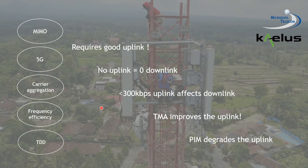We must also remember that we have two things, basically three things that degrade the uplink. Interference, that is all in the operator's hands. Thermal noise, that will be solved by TMAs. And passive intermodulation, that can severely degrade the uplink. That is solved by using good equipment and doing good installations.